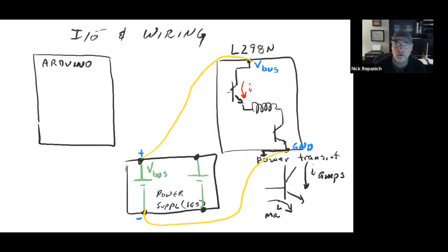And now you know a bunch of stuff. You know schematically, electrically, that you've got power going the right way through there. You're looking for those three things: I've got power, there's the switch, there's the load, there's another switch, and boom, we made it back. And you always have to get back to the ground of that power. We don't want to get back to that one. You've got to get back to that one.